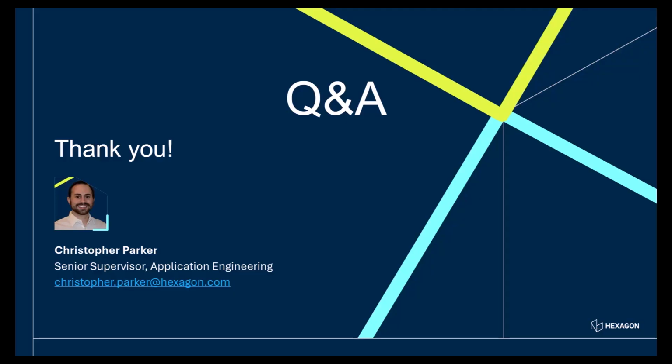Great. Okay, perfect. And how accurate is the rest stock preview? So it is a more general representation, depending on which one of those quality settings that you use. It's definitely accurate enough to provide a good jumping in point. But if you want to do the full simulation, that's why it's important to use our module that we had before, where you still click that simulation button, and then it's doing the true material removal rather than the representation. But it is close enough to give you a jumping in point that is going to save you a bunch of time if you're hopping around or making changes.